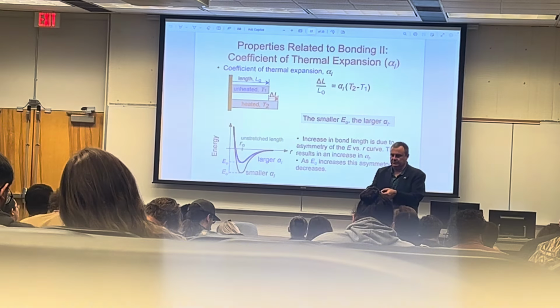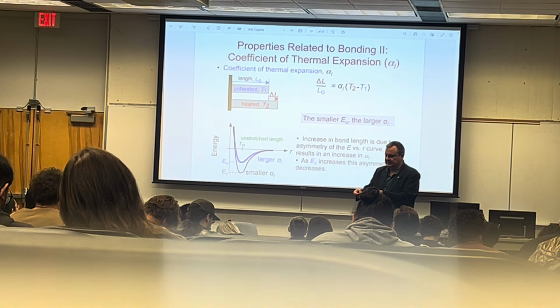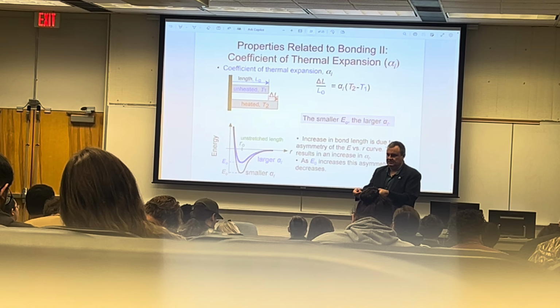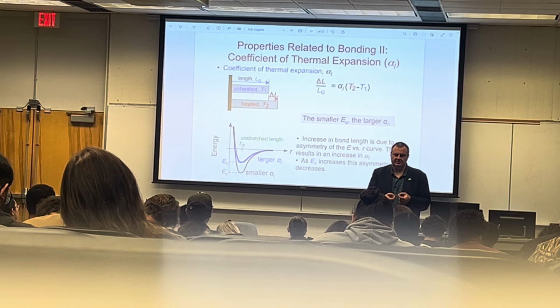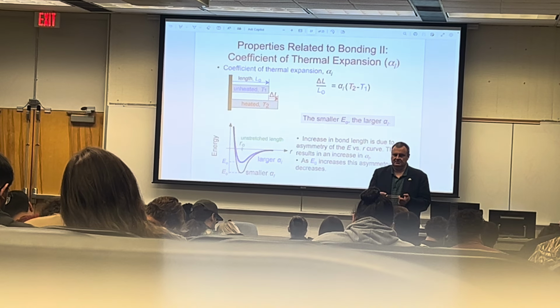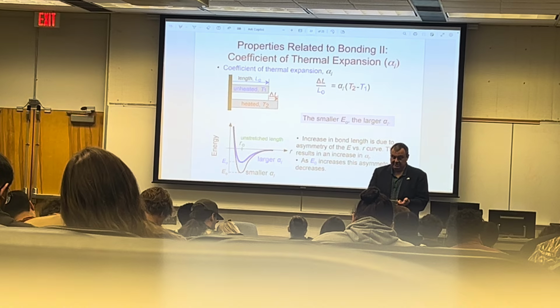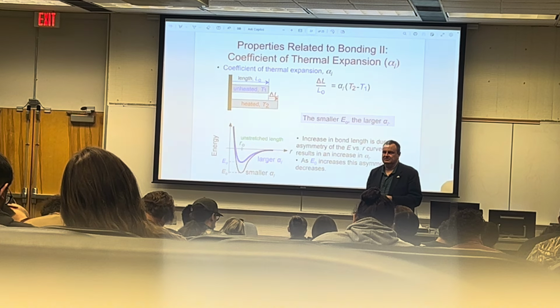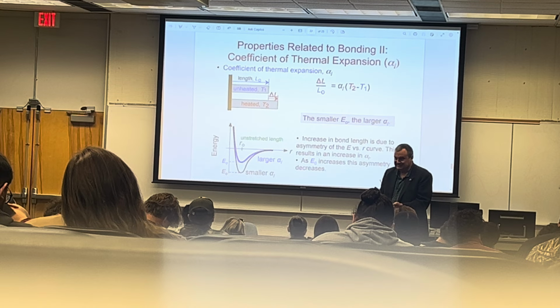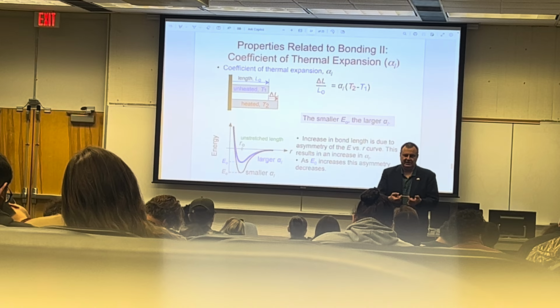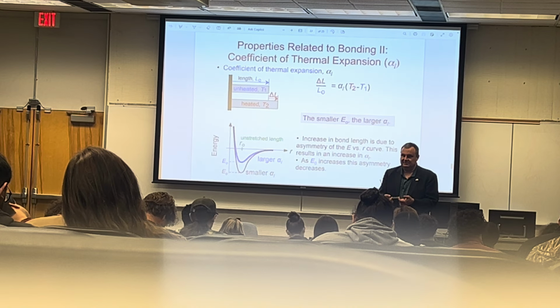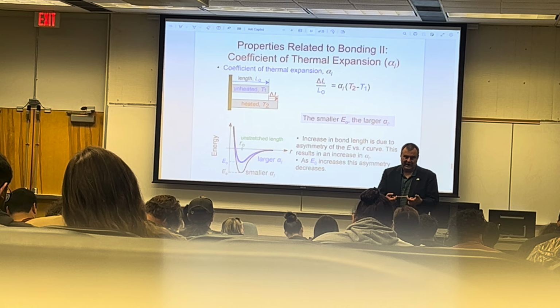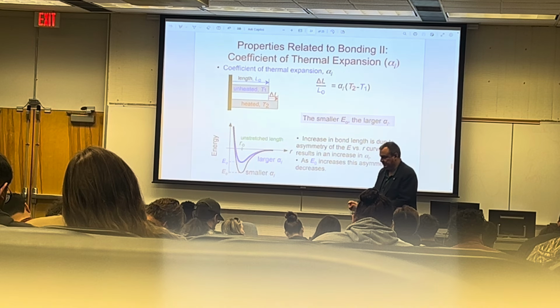The length was this, and after I applied the force, it became that. Did it increase or decrease? It increased, so it's a plus. Did I put it in tension or compression? I put it in tension. This is why tension is positive.